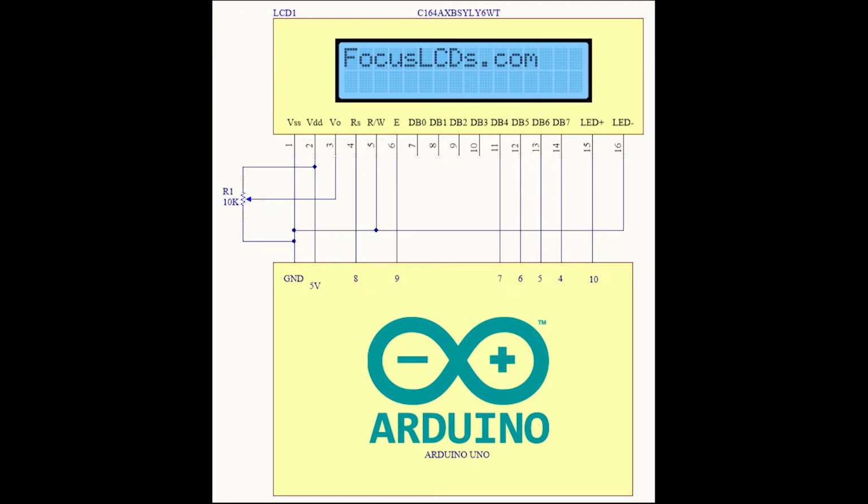DB4 through DB7, which stands for data bit 4 through data bit 7, is for manipulating the text and is controlled by the Arduino. RW, which stands for read-write pin, is set low. That means it is tied to the ground, which indicates that we are writing to the LCD registers, not the other way around. VDD is plus 5 volts. This comes from the USB connection to the PC, and VSS is ground. It's your reference for the LCD. The backlight is controlled by Arduino pin 10, which functions as a pulse width modulation output.